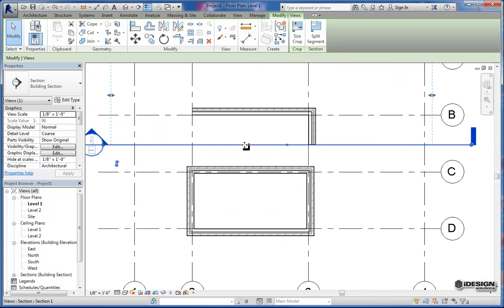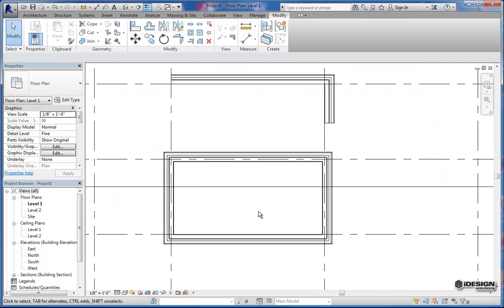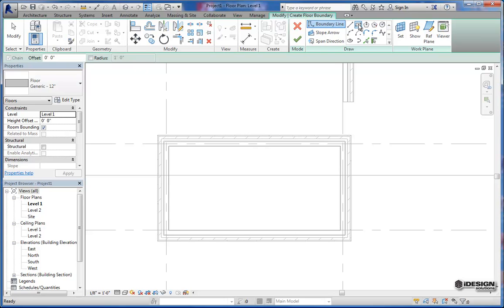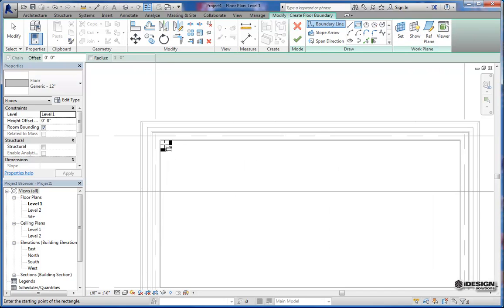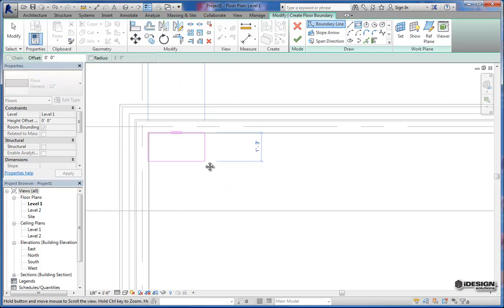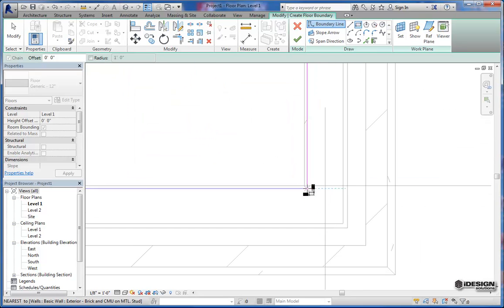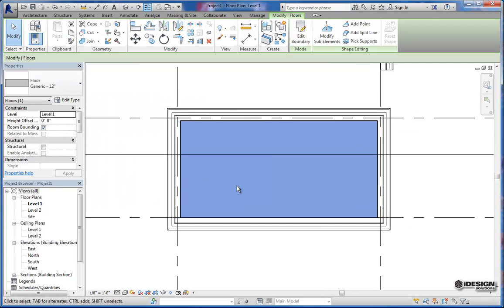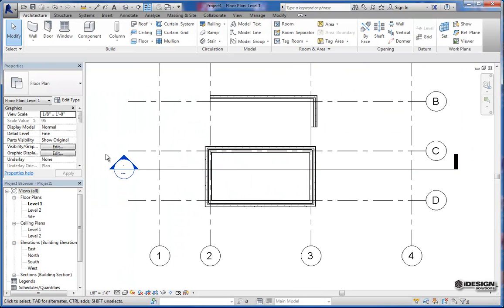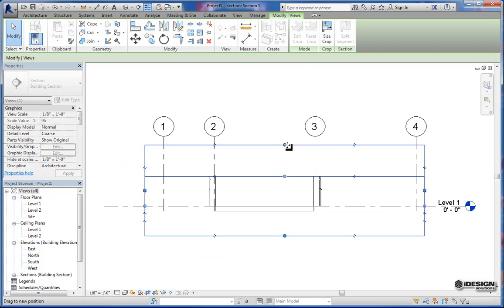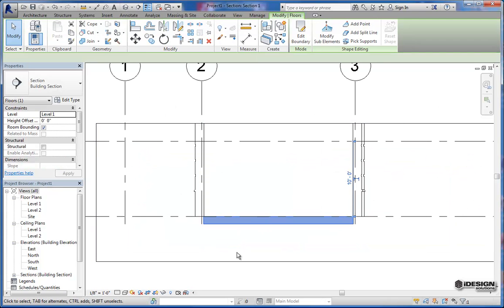Another place that it's helpful is with floor elevations. If I was going to put a floor in here, I'll just start this quick simple floor, and again I'm just going to draw that using a rectangle, and we'll put that to this corner right here. And we'll accept that. Now I didn't pay too much attention as to where that floor is, but if I go into my section and expand this view just a little bit, I'm starting to see that floor here.